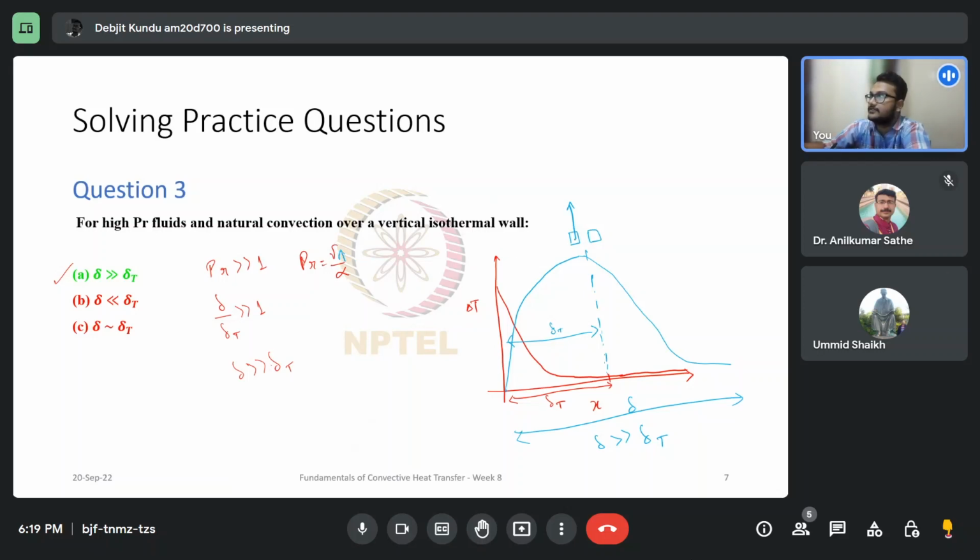So that high viscosity is actually pulling these packets of liquid far away from the thermal boundary layer as well along with it. The region over here attains some momentum due to temperature difference. Now that momentum is diffused in the far field as well due to the property of viscosity of that fluid, and since it is high, it keeps extending to considerable lengths.